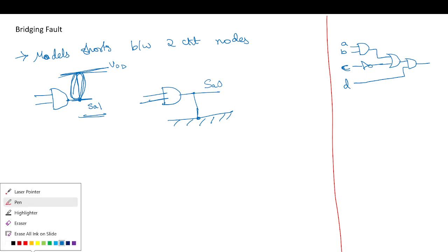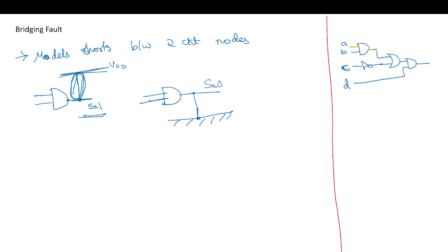Now if I consider this path and say that this gate is adding 1 unit of delay, this gate is adding 1 unit delay, 1 unit delay, the total output will be obtained with 3 units of delay. So similarly this path, whenever an output has to come through this path, these gates are adding some delay, so it's a cumulative effect.